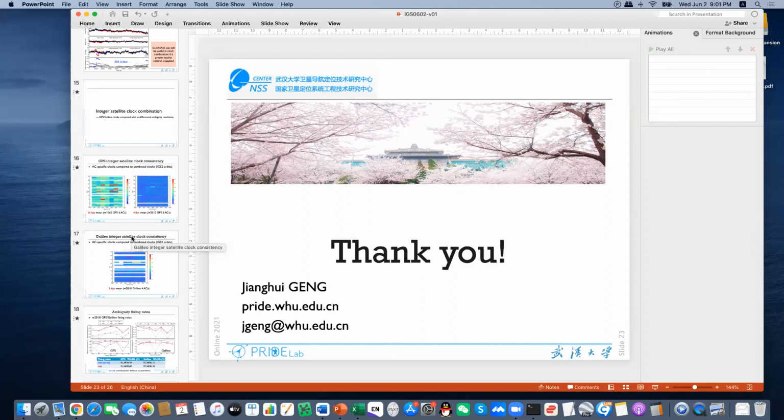But if you're talking about the context I was talking about in the slides, for the GLONASS clock combination quality control, we just use the clock consistency among different ACs to identify the bad GLONASS satellites with the bad combination clocks. So if you have the clocks from different ACs whose differences among them are so large, then you cannot have a good combination result. So in this case, you can remove them in the final combination results, and then that kind of outlier clock will not impact the PPP solutions.